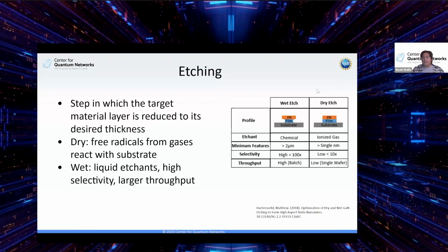Okay, now then, you've done the photolithography. You've developed it. Now you just need to etch away the part of the film of your target material that you don't want. So what etching essentially does is exactly that. It looks at those holes in the photoresist and it starts etching away the film underneath. So there's two different types. The main one, and this is the one that I've done pretty much exclusively, is dry etching. And one of the common types is called RIE, or reactive ion etching.